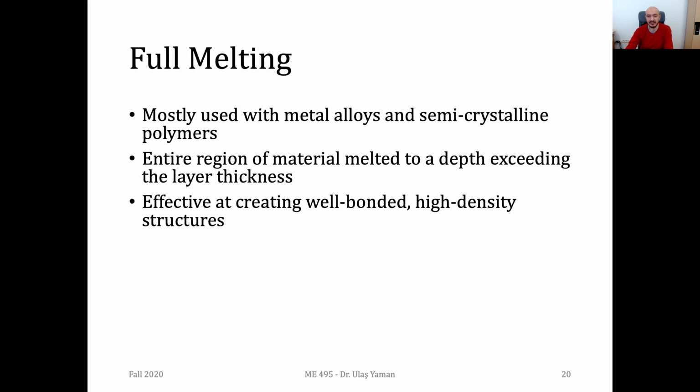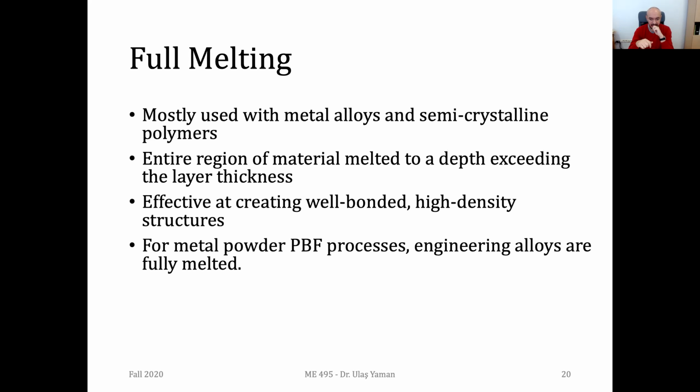Another thing, this melting should not continue so long. Otherwise, again, you'll lose dimensional accuracy. It should be at the critical value, and it should be solidified once the process is done on that layer. And the advantage is that you'll have a very well bond between the layers since they are melted, and it's mostly utilized especially for metal alloys.